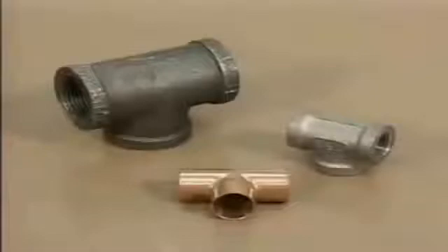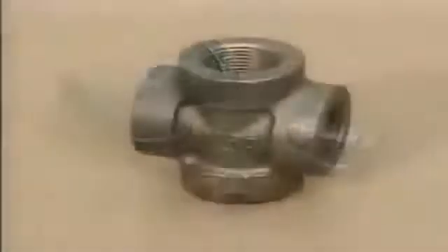Another function of pipe fittings is to provide branch connections. Pipe fittings that provide branch connections are used to divide the flow of fluid in a pipe run into two or more branches. One of the most commonly used branch connection fittings is called a T. T's are used to join a main pipe run to a branch pipe run at a 90-degree angle. T's come in a range of sizes and designs, and they can be threaded or welded to pipes.